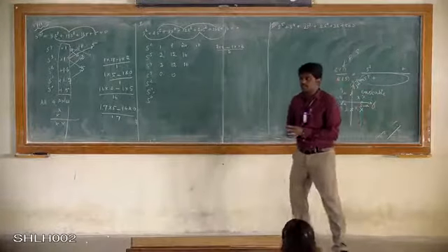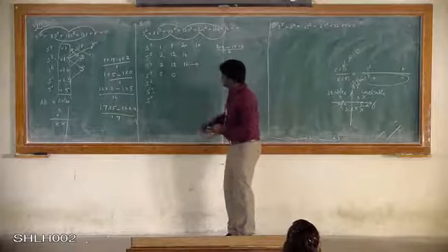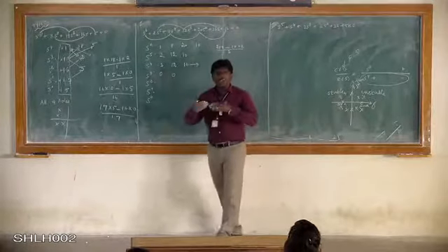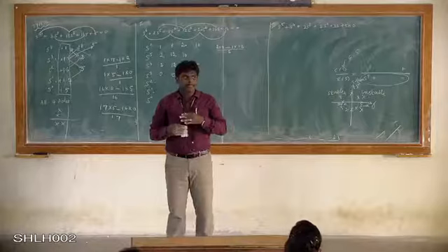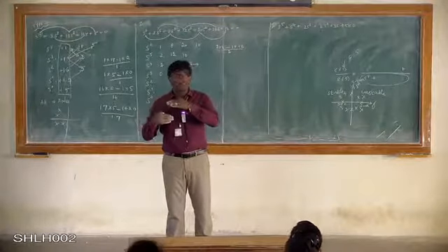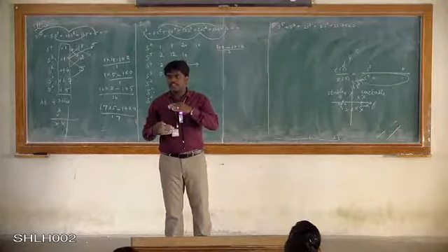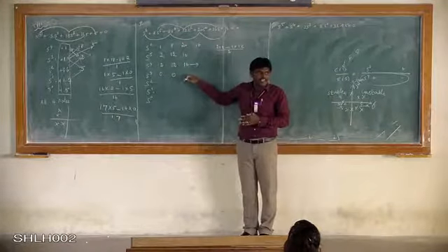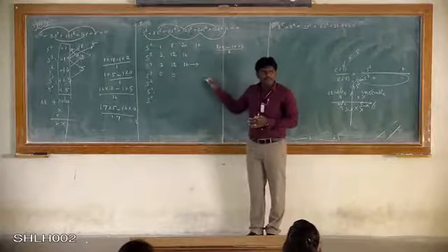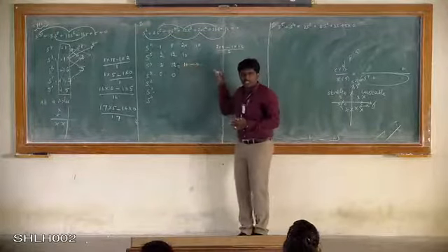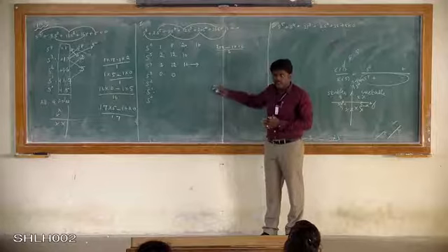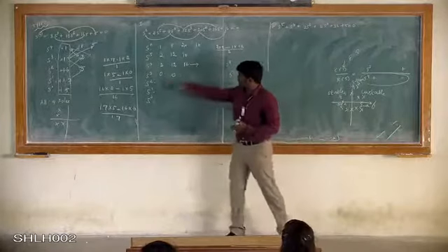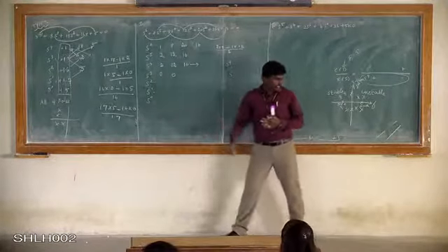So now what we will have to do is that you will have to write out this particular equation and take the differentiation. You have got a fourth order equation. If you differentiate once, s power 4 becomes s power 3, right? Because from s power 4 to get the s cube row, when we try to solve, this row is becoming full of 0. So write out this equation, differentiate it once, right? So if you differentiate the s power 4 equation once, it becomes s cube, then that equation can be written over here.